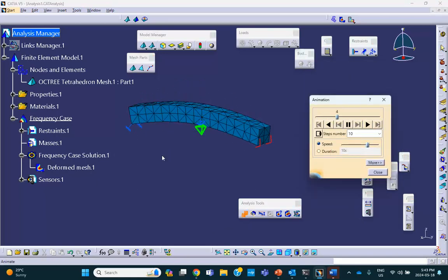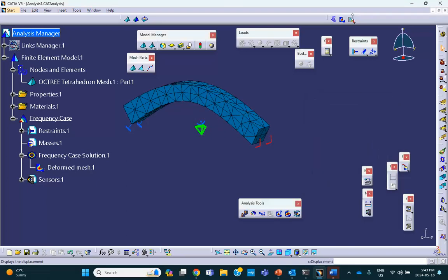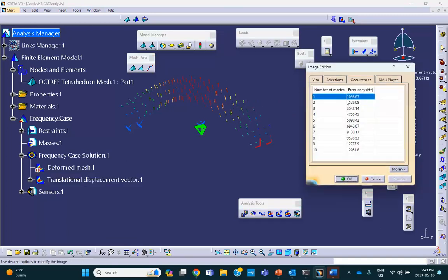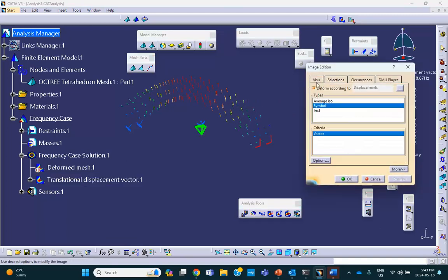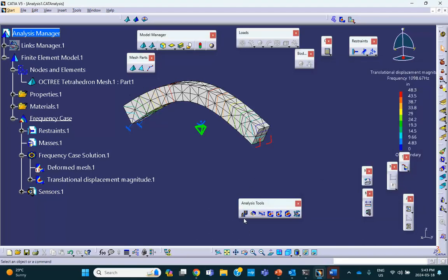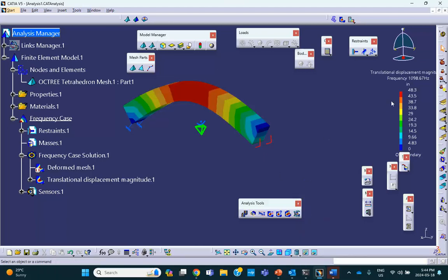Very good. Now, what about displacement? This is the deformation. What about displacements? Well, you're going to get like that. And if you say, show me the average ISO, this is the first bending frequency that we're interested in. And the displacement is, let me change the rendering here for you. Material shading. Right. Look, 48 inches. The whole thing was 10 inches.